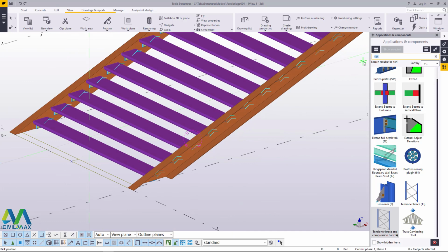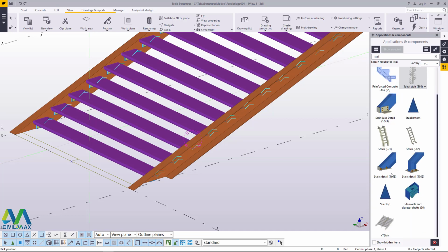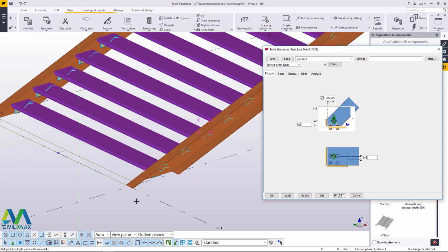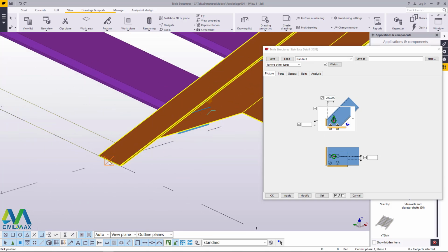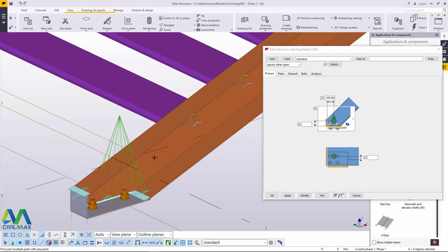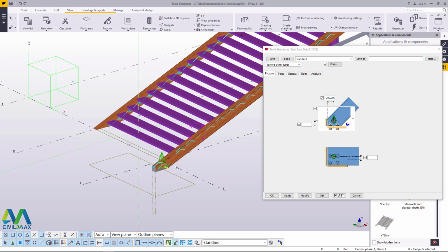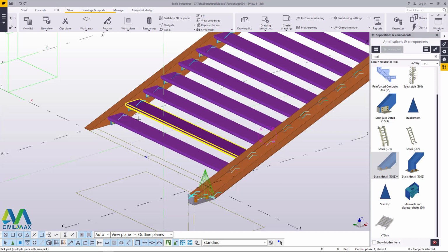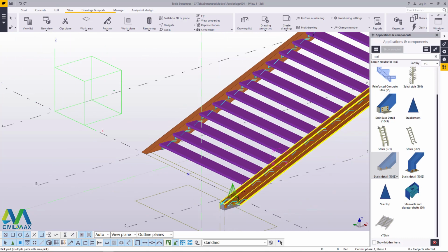We'll come here and type staircase, and click inside here and scroll down, and I want to double click on that macro or extension, and I'll pick this choice, select this stringer and pick at this far end, and give it some time to place some boltings here that will help us in anchoring the bottom end of our staircase to column bases that will enable the stringers to be held firmly on top of the concrete that will be placed here later on once we are done.